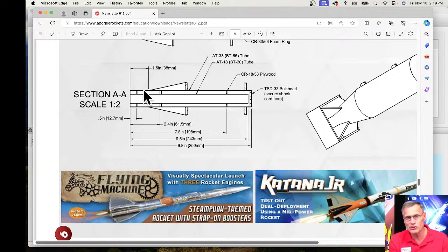There's actually a manufacturing code in rocketry. In order for a rocket to be considered safe, the external temperature of the case after firing has to be under a threshold. And if it's above that threshold, it's not going to get safety certified. It's because of this reason, so that if you pick up a motor after it's fired, you don't get an instant burn. It's going to be hot, and you're going to feel it, but it's not going to blister your hand. At least it shouldn't. So your parachute, even if it's plastic, can probably withstand a significant amount of exposure to just laying on the side of a rocket motor after it's fired.